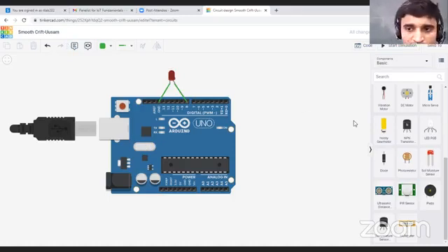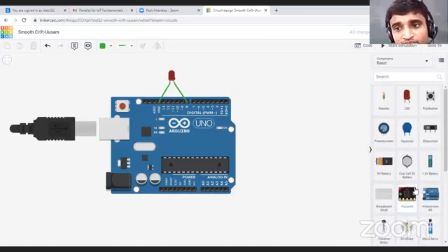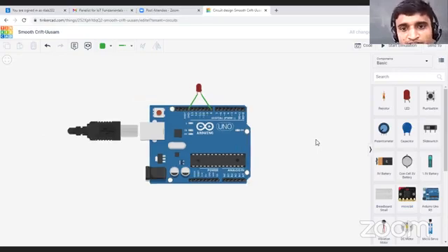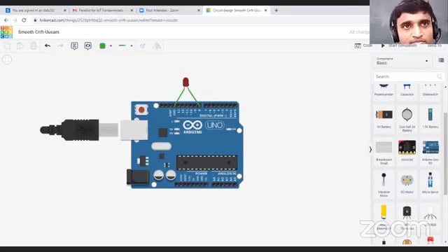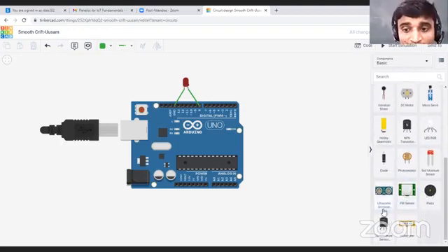You just apply different sensors: soil moisture sensor, photo sensor, ultrasonic sensor. Now, based on the sensor, how to apply? Suppose we take one of the smart agriculture applications. If I take a small application, like I want to check my farm field weather, getting some parameters of temperature and humidity, then I also require soil moisture. Then I can use DHT11 sensors for temperature and humidity, a soil sensor, and one more, I can use the ultrasonic distance sensor.